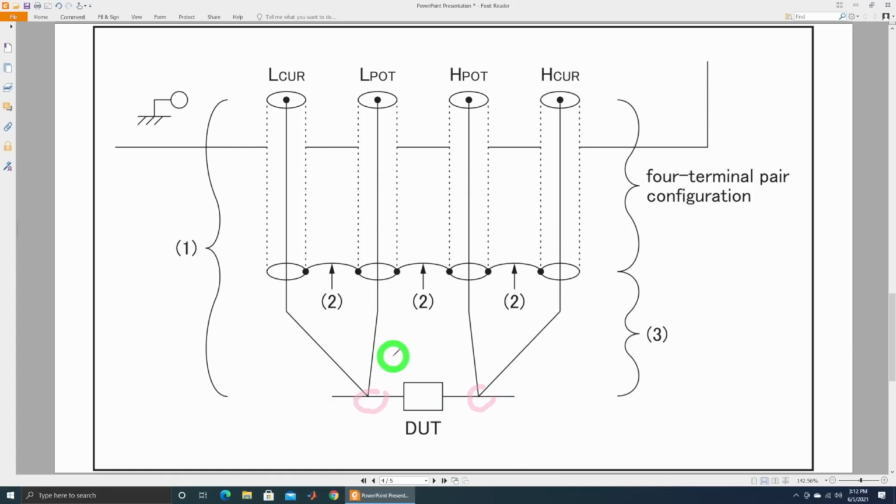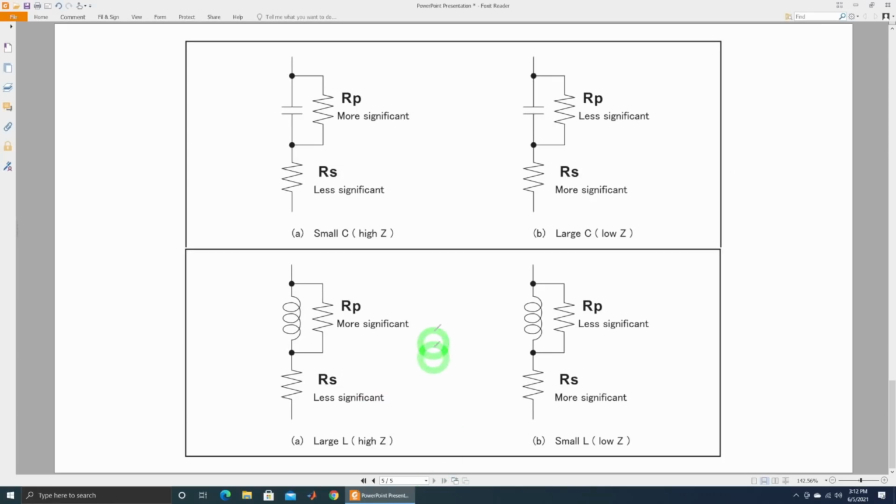So yeah, it's pretty nice and elegant, and it's a very standard technique, of course, nowadays to measure any kind of LCR devices like this. So then we're going to take a look at this. But there's also a little bit more about why the frequency matters. Well, as I said, no component is a pure capacitor, inductor, or resistor. There's always a parasitic element associated with it.